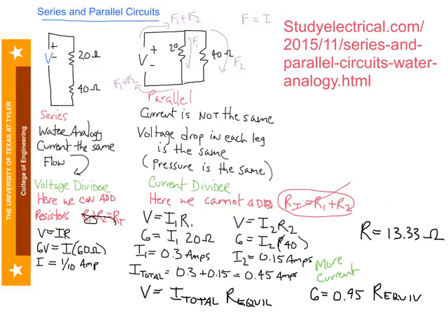All right, so what does this tell me about the equivalent resistance? Well, when you do the resistance in parallel circuits, the equivalent resistance should always be less than whatever the lowest one is. My lowest one's 20, and 13 is less. It's a little bit of a sanity check on my results. So it is making sense.